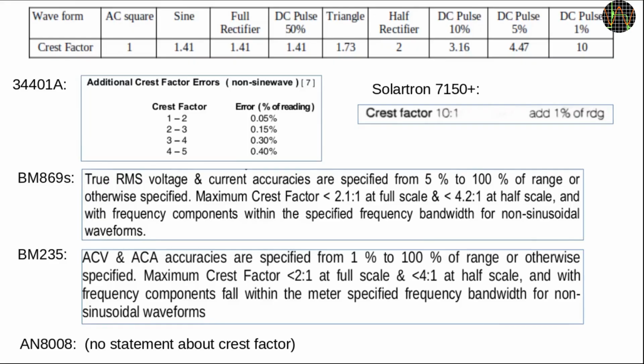Another pitfall to watch out for is the crest factor. I mentioned the crest factor before when I explained the different waveforms I used for testing. In that little table here is a quick summary ordered by increasing crest factor values. The crest factor is important because it messes up the way most True RMS circuitry works. There are exceptions. Some very expensive bench multimeters sample the waveform into memory and determine the RMS graphically, just like a digital storage oscilloscope.